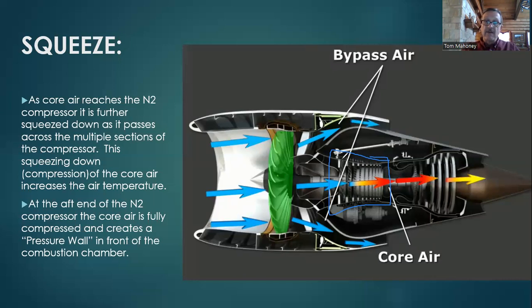These things right here are rotors. Now, you can remember they're rotors because they're the part that actually spin. The stators are little fins in between the rotors that redirect the air to the next rotor so that the rotor can grab the air more efficiently and keep pushing it rearward.